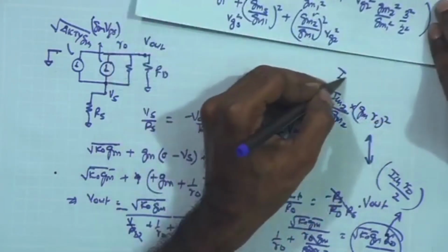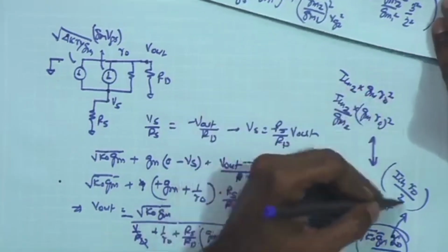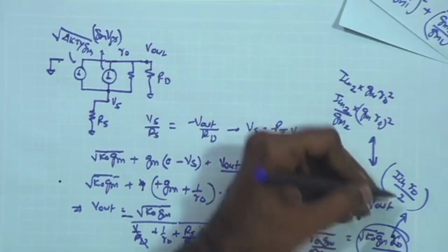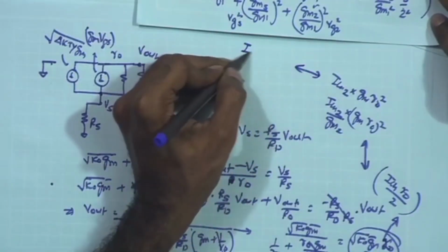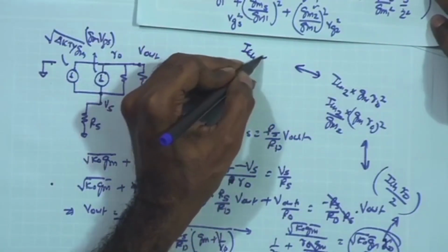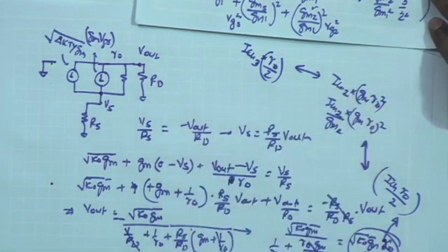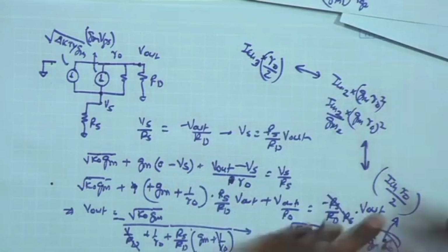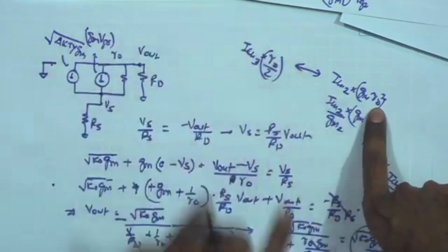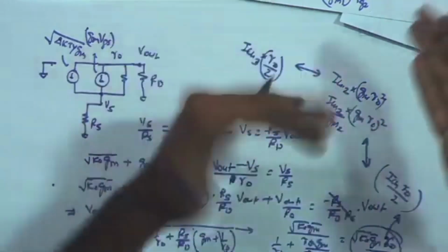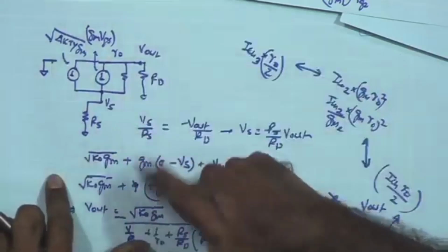So basically I have ICH2 getting Gm times Rho square, whereas the ICH of the cascode device is just having a factor ICH times Rho by 2. So here you are having Rho by 2 and here you are having Gm Rho times Rho, right. So magnitude point of view, once again the same conclusion, that the overall noise voltage at the output because of the cascode device is Gm Rho times smaller as compared to the devices which are connected to the VDD and ground, that is the M2 and M5.